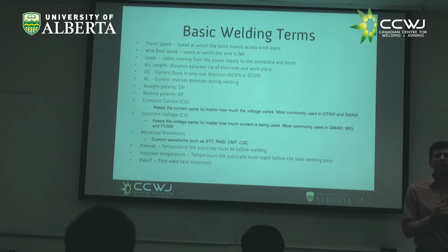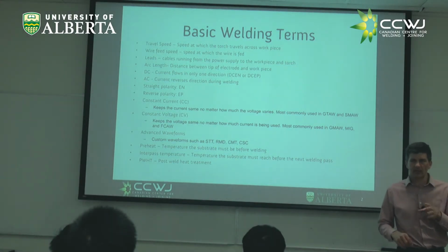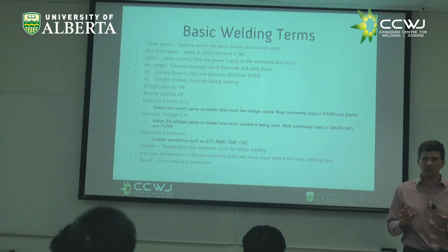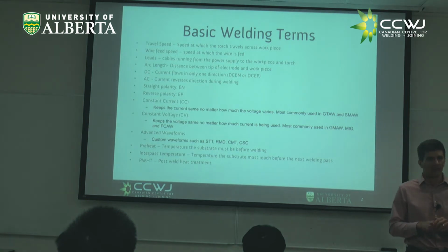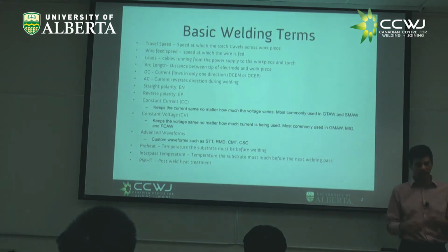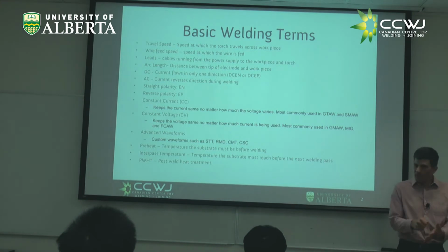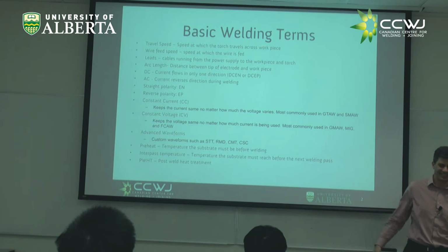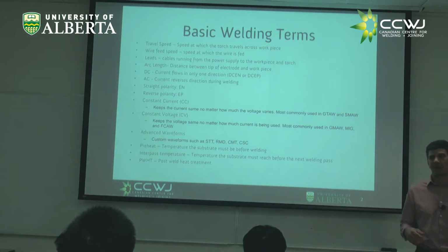So if I'm welding stainless steels, do you think I care about the interpass temperature, or I just let the temperature increase forever? No, right? So, for example, in stainless steels, interpass temperature is very important. And the consequence of interpass temperature is not just words. It means a welder made a pass, and the welder has to step back and wait. But you're paying the welder a welder wage, while the welder is just waiting. Of course, companies hate this. On the other hand, the risk is sensitizing the steel, right?